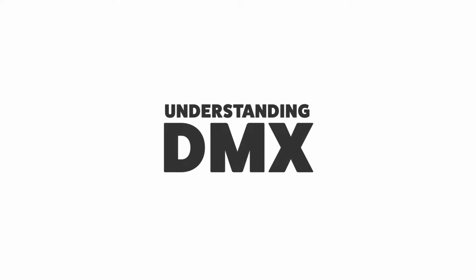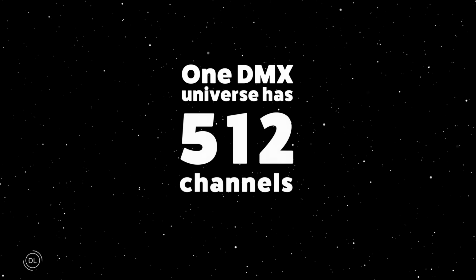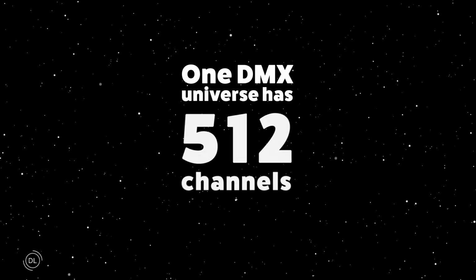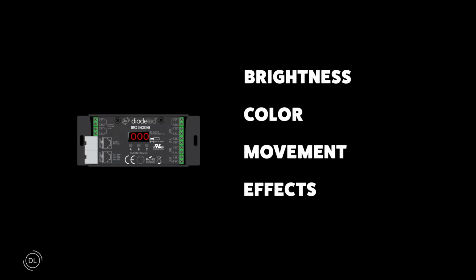To understand how DMX works, let's look at how systems can be designed. One DMX universe is made up of 512 channels, each of which is controllable. Each lighting fixture is assigned to a respective address, allowing independent lighting control among its channels. Each controllable channel is assigned to a different parameter of lighting control, like brightness, color, movement, or effects. Each address depends on the number of channels within that specific lighting fixture.